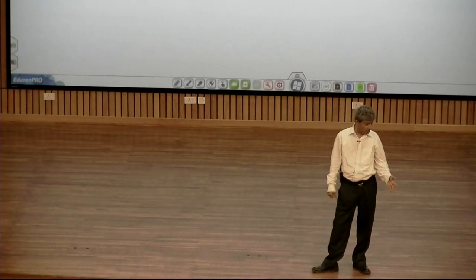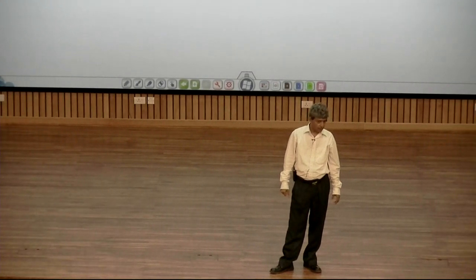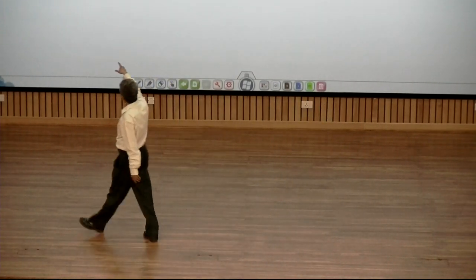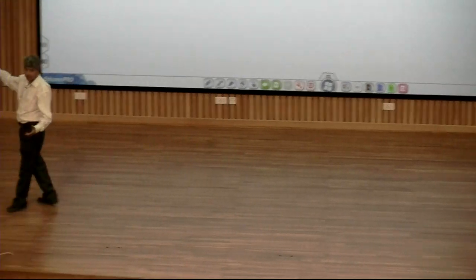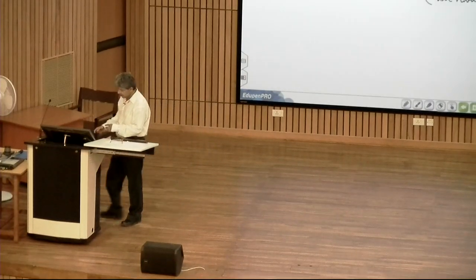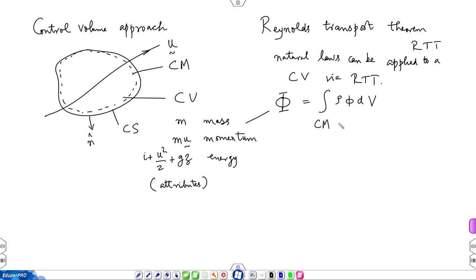As rapidly as the local fluid velocity, right. So, the distortion rate of Cm is really the velocity field. So, you have to keep that in mind for understanding Reynolds transport theorem. Okay. So, this phi is evaluated at time t, then Cm is equal to Cv. Time t could be t equal to 0, but at later times Cm and Cv are not the same, but they differ to an extent that depends on the local velocity field.